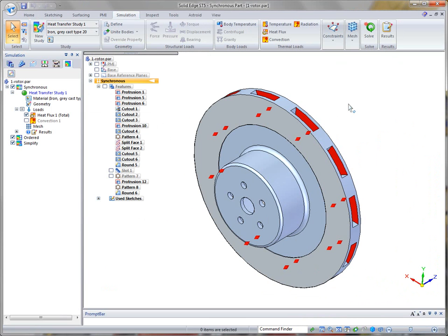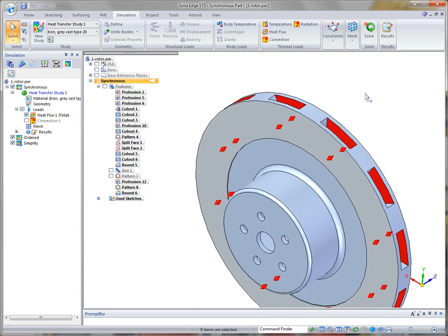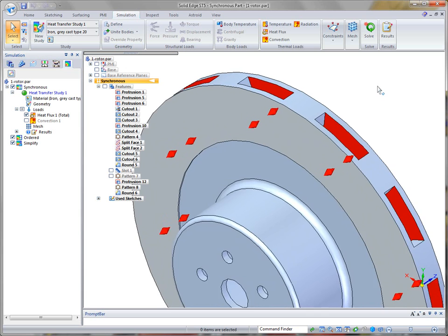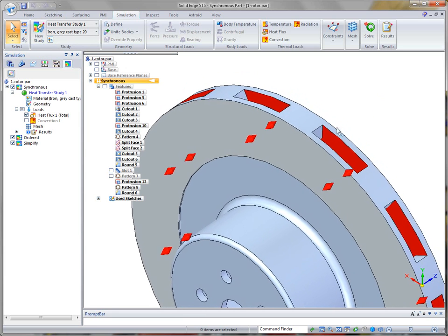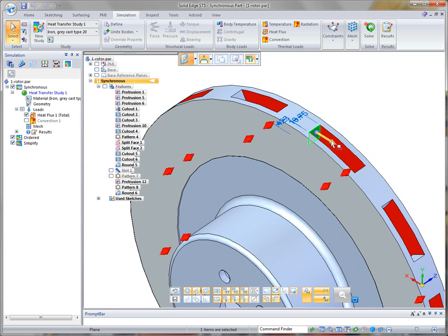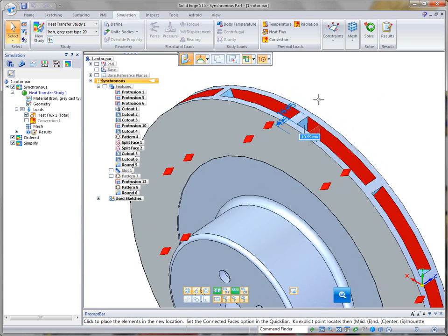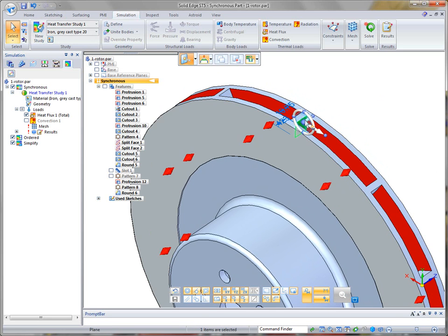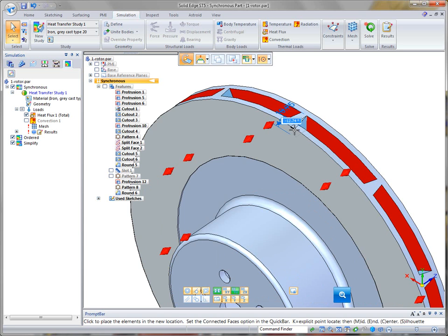So what we want to do is drop that a little bit if possible. Not a lot of changes to make it drop drastically, but we can make some changes to get the temp down just a little bit. One thing is to thin these out. They're way too thick. So I'm going to make a modeling change, and I'm going to take these down to 12 millimeters. I'm then going to move it up, and if I pick this face and move this to the corner, I can then rotate and maybe put a little bit of an angle face. I'm going to put minus 12.